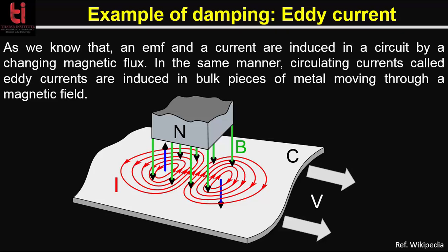Now, the flow of electrons in the conductor immediately creates an opposing magnetic field, which results in damping of the magnet and produces heat inside the conductor, similar to the heat built up inside a power cord during use. The amount of energy transferred to the conductor in the form of heat is equal to the change in kinetic energy lost by the magnet. The greater the loss of kinetic energy of the magnet, the greater the heat build up in the conductor and the more forceful the damping effect.